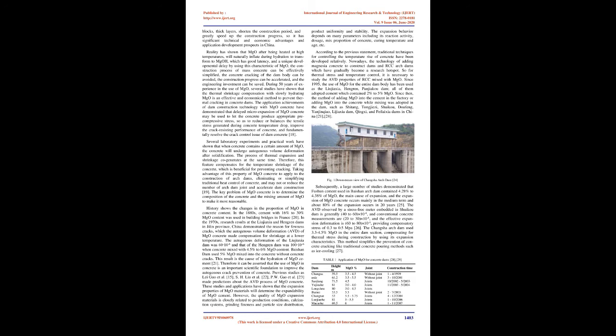The application achievements of dam construction technology with MgO concrete have demonstrated that delayed micro-expansion of MgO concrete may be used to let the concrete produce appropriate precompressive stress, so as to reduce or balance the tensile stress generated during concrete temperature drop, improve the crack-resisting performance of concrete, and fundamentally resolve the crack control issue of dam concrete.